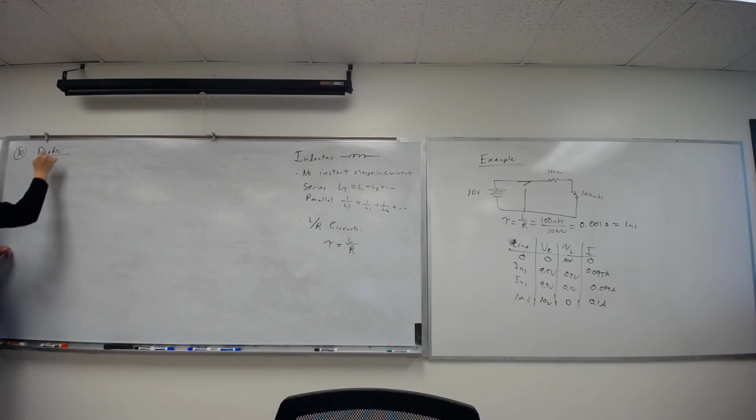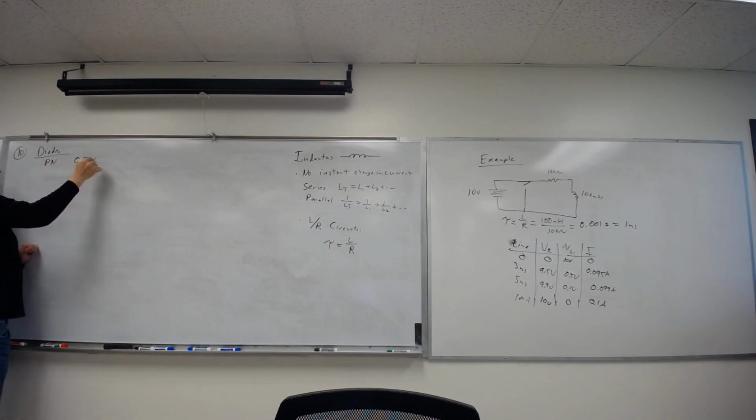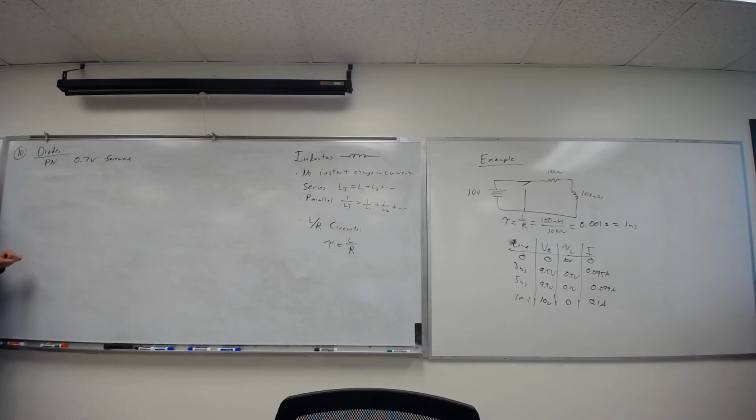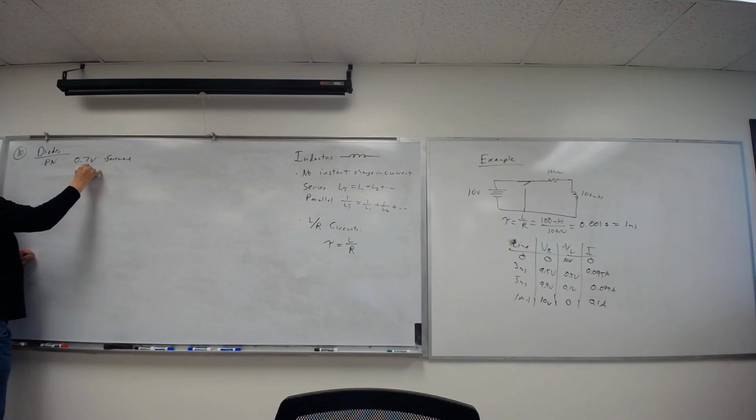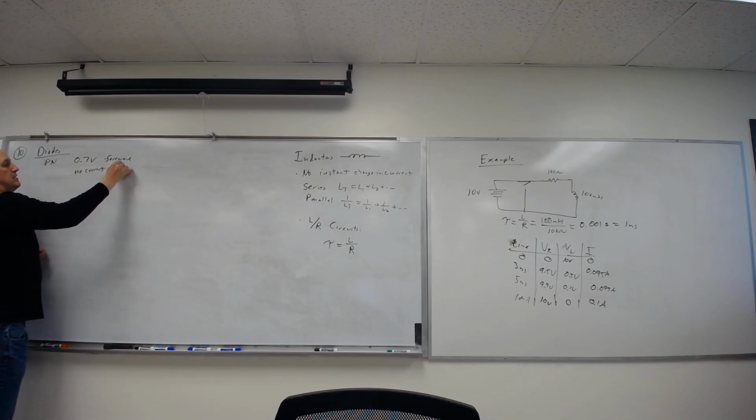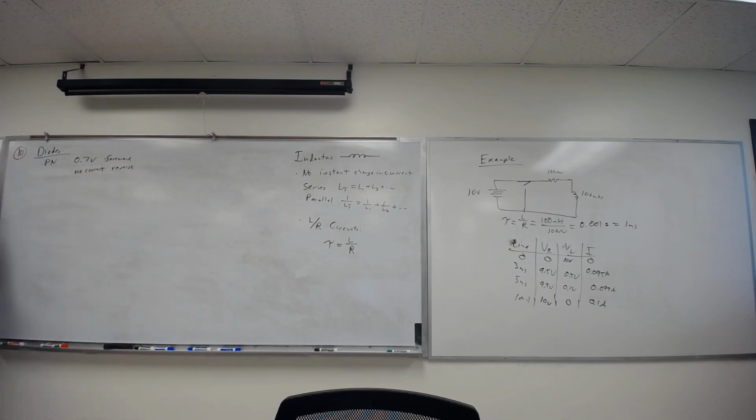So when you look at these p-n junction diodes, remember you need 0.7 volts forward bias to open them up. Reverse, no current. There's really 3 circuits. I'll let you go back to the homework. I'm not going to go back and draw. You can either forward bias it or reverse bias it. Forward bias, current flows after you pay the 0.7 volts. So we'll do it real quick.